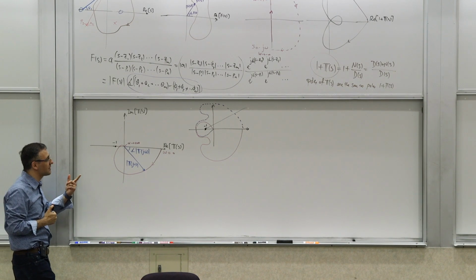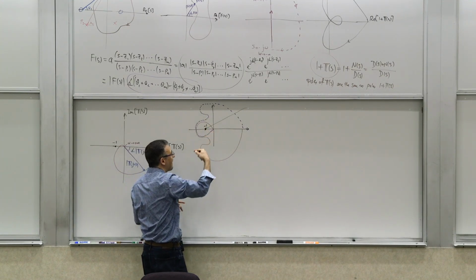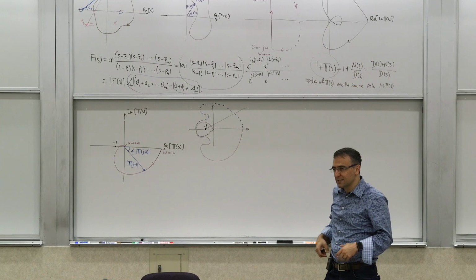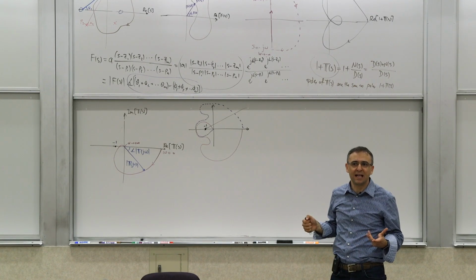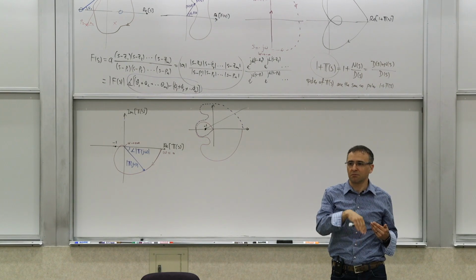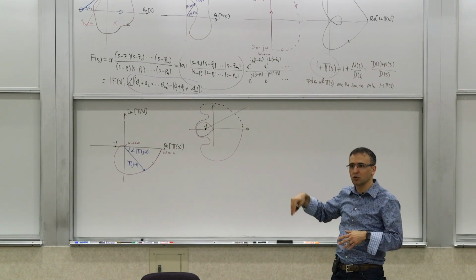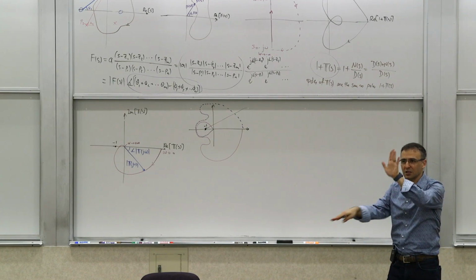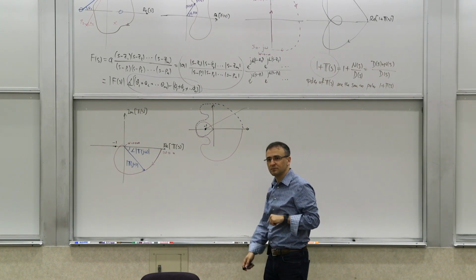So you have to be careful when you look at these pictures, because if you ignore the other half of it, you may not see the other part of the plot. So that's unstable, meaning that you can get unbounded output with a bounded input. You can hit it with something finite, and then it can eventually grow, maybe exponentially, or as a sinusoid that grows exponentially to infinity.